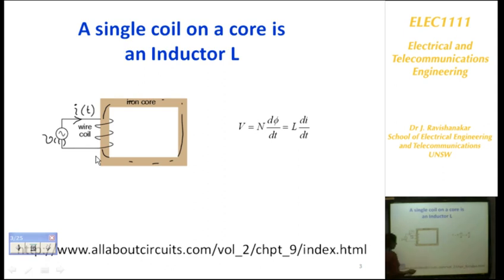As soon as the current flows through the wire, this will produce flux around the wire, like this. Whenever you have a current flowing through any wire, whether it's DC or AC, there will be flux produced around the wire. In the case of DC, this flux will remain constant because the value of the DC voltage is constant. Whereas if you supply AC to a wire, then the flux will be changing instantaneously, just like the current or the voltage will change instantaneously. So this is a flux produced by the AC current, and this is time varying flux phi(t).